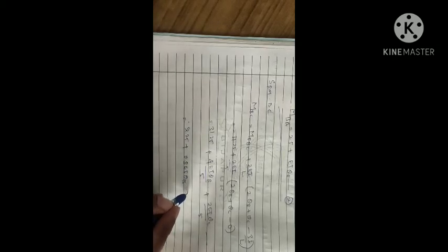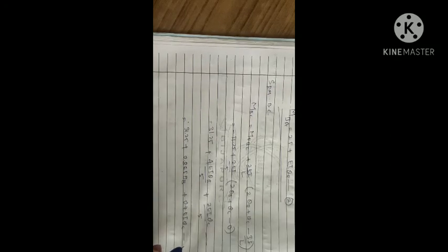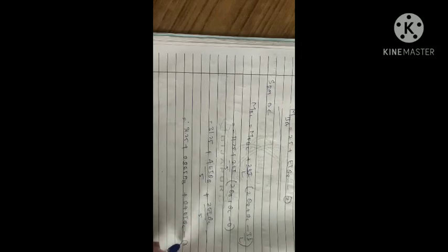Okay, so simplifying this equation, we will have 31.25 plus 4 by 5, which is 0.8 EI theta B plus 2 by 5, which will be 0.4 EI theta C. So this is the simplified equation, equation 3. Okay, similarly now go for